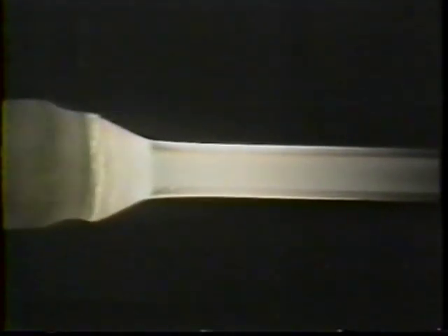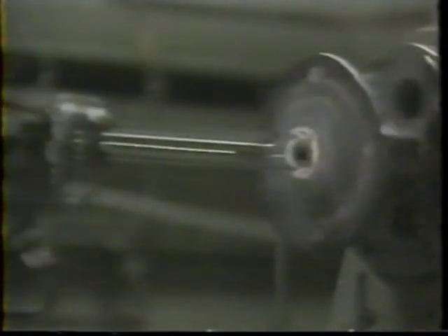For multi-mode light guide preforms, the mixture of gases is changed slightly during every pass so that each layer deposited has a slightly different density and index of refraction. For single-mode preforms, over 90% of the passes are for additional cladding material around the core.